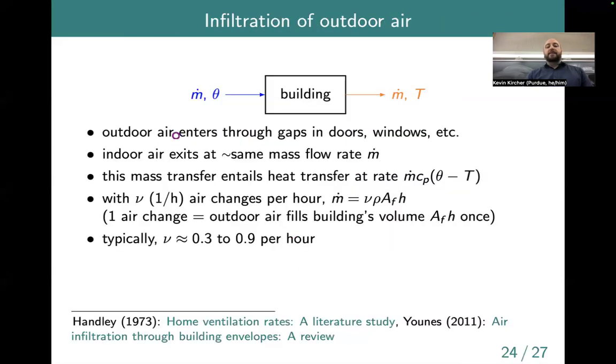So that is a way to back up what the m dot is. You specify nu, we know what the density of air is, you can find the floor area of the space quite easily, and specify a ceiling height. You could imagine this is, I don't know, 4 meters or something like that in this room. So you can easily specify all these things, and that gives you a rough, time average mass flow rate.